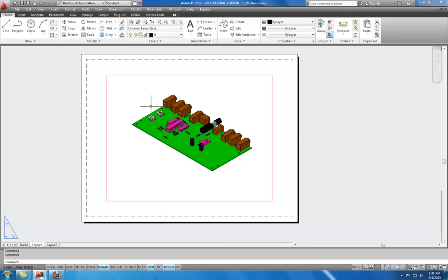This is what's called paper space, and paper space is designated by this right triangle in the left-hand corner, and it's used for printing applications. When we do our drawings, we work in model space, and so we have these tabs across the bottom, and what these tabs do in paper space is they allow us to put together a book, and so we can put together page 1, page 2, and these are called layouts. We'll explore layouts in Module 8 in great detail.